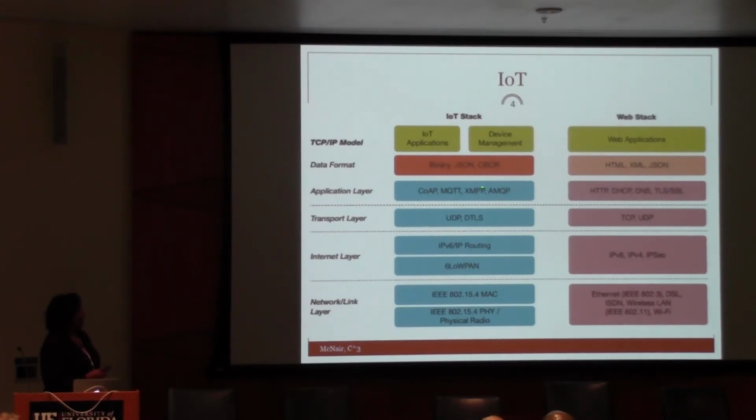And we're continually seeing new developments at the application level like CoAP and MQTT for manufacturing, and other applications for just having a device that's simply reporting little text blips or little messages that some sink somewhere is recording data from and telling the network to respond to. So this stack is a bit different from the original stack in that it has options, it has flexibility, it has varying capabilities for the nodes, but they're expected to all be able to communicate in the same system.